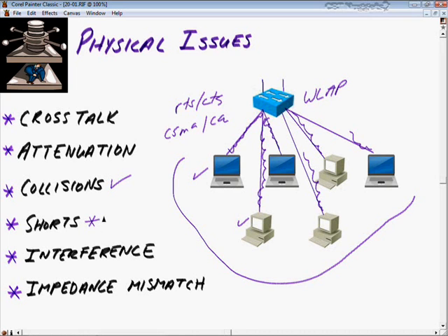But while we're here, I'll go ahead and mention that you can get network cable testers. Network cable tester, for example, from a company like Starin. There's many of them, but these will help you locate where that particular short is in the cable, so you can either repair the cable or replace the cable. Sometimes, because of the difficulty of getting access to cables and the cost of replacing it altogether, finding the short and repairing it at that particular point is a much cheaper and much more efficient option.